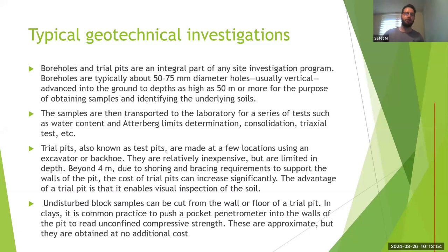Generally speaking, it also depends on the country you are in. For example, in Europe, the minimum requirement for the diameter of the sample would be 54 millimeters. So your borehole is not going to be less than 54, and you usually start at a lot larger diameter. We will start at about 114, 124 usually, and then we gradually drop the diameter of the borehole.